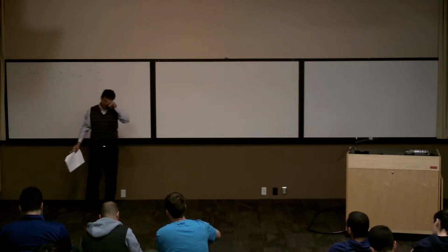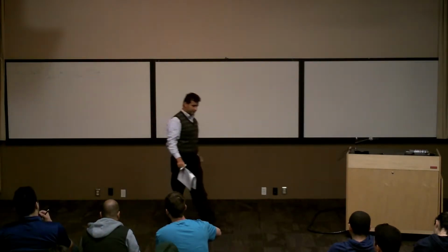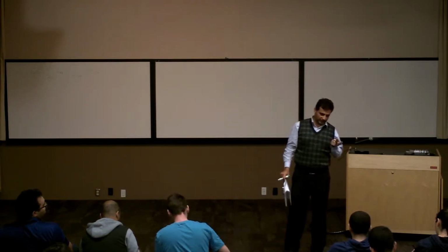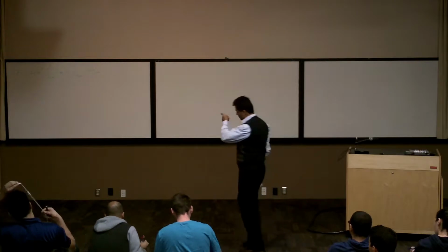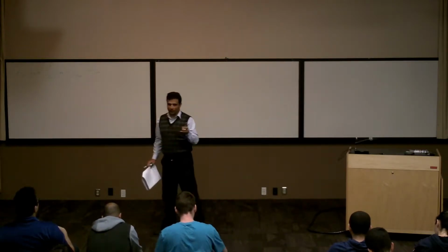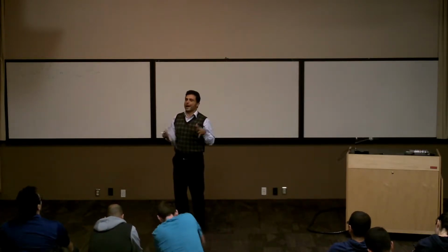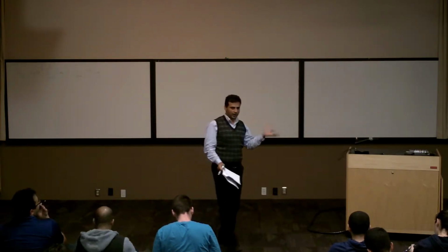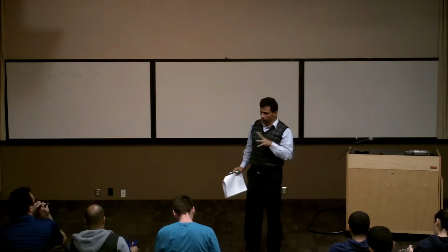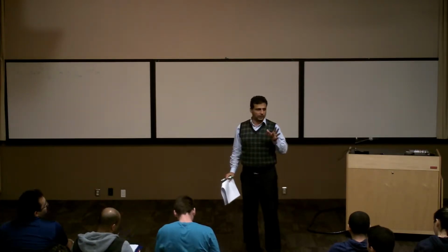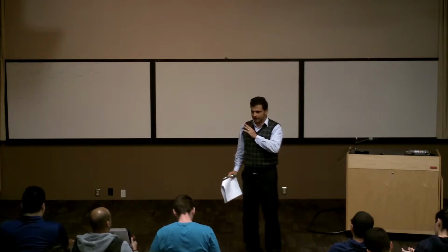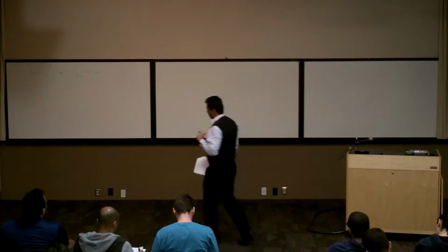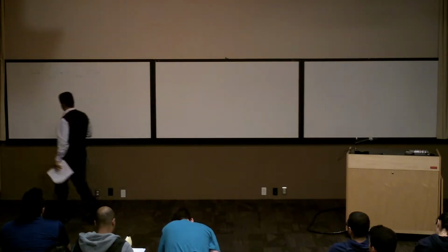This is the equation, the last thing we covered, using it was calculating the inductance of a single phase system or two-wire system. We calculated that one using this equation. Basically, we had only 2 wires. This equation was for m wires. We have m wires. Each one is carrying some current, for example, I1, I2, I3. And the only condition we had, I1 plus I2 plus IN is going to be 0. That was the only condition we had. We calculated the inductance for a single phase system, now calculating the inductance for 3-phase system.